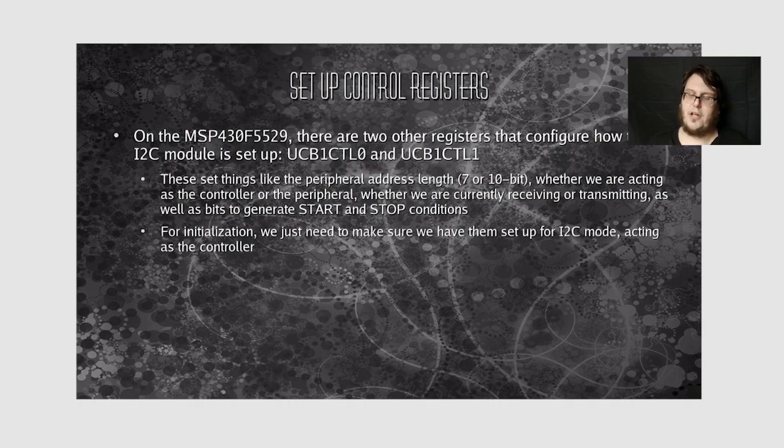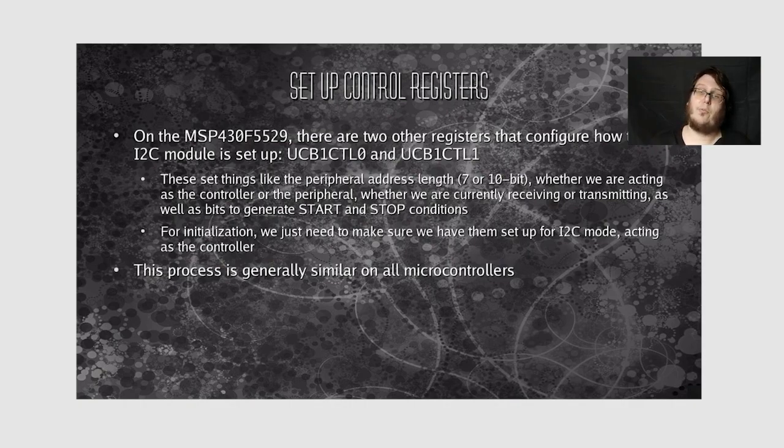For initialization, we just need to make sure that we have them set up for I2C mode, acting as the controller. And this process is generally similar on all microcontrollers. You're going to be setting whether you want 7 or 10-bit peripheral addresses, whether we are acting as the controller or the peripheral, and then there's going to be bits to generate start conditions, stop conditions.